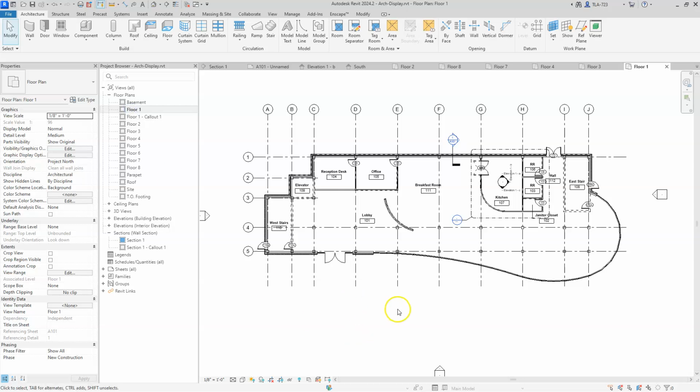The point is, I've done a lot to override the graphics in this view. Okay, so I want to apply that to another floor without having to go back through painstakingly changing all of those individual visibility graphic override values to look the same. I can save that work in a template. You can sort of think of it as a visibility template that looks at all the overrides that I've applied to this view, and it saves them so that I can just reapply them to another view quickly and easily.